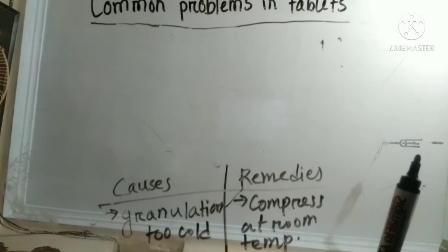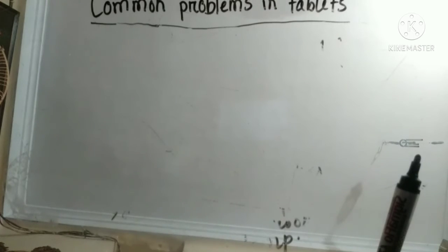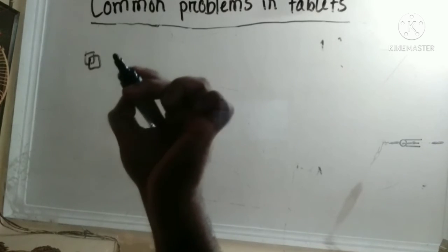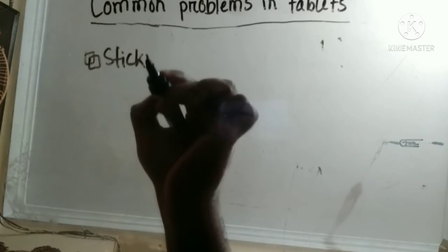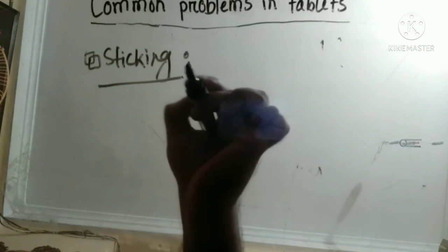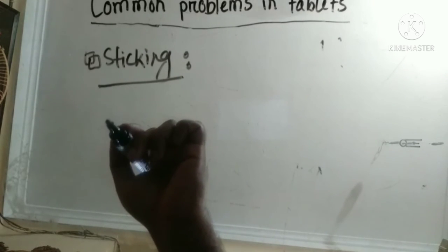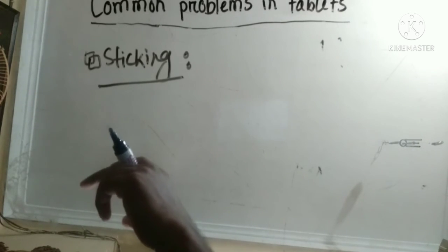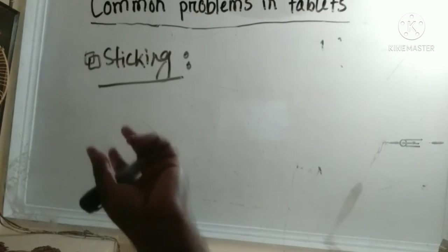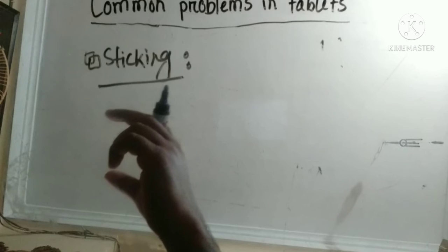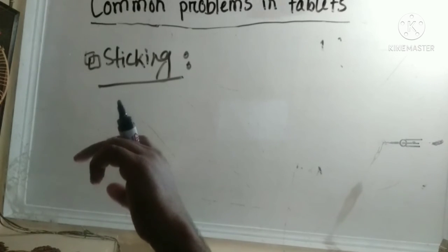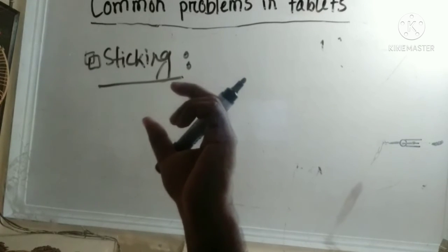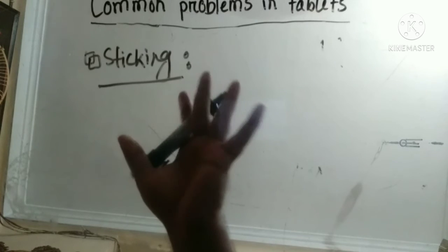Sticking is actually when granules adhere to the die wall and thereby lower punch of the tablet cannot move freely.